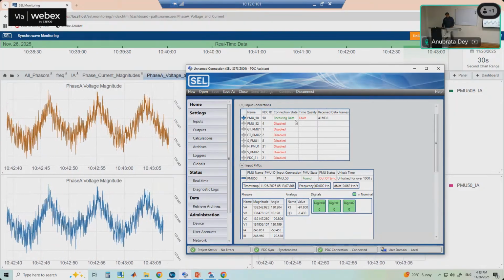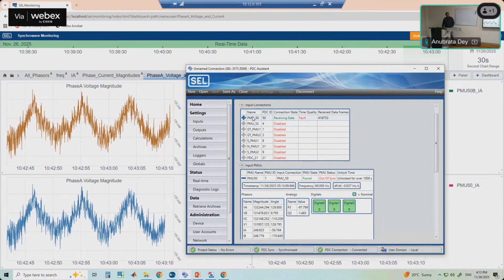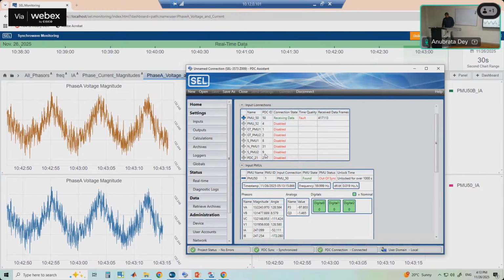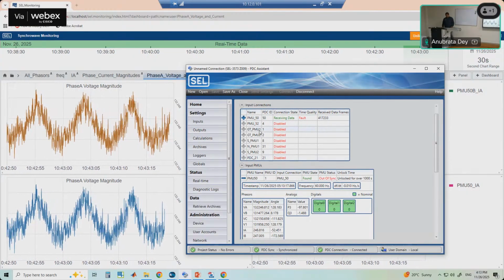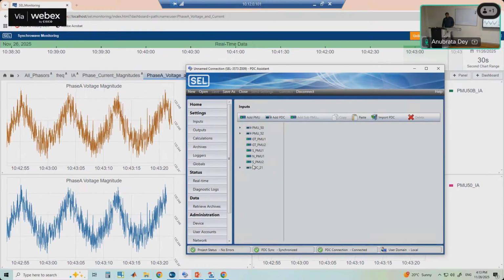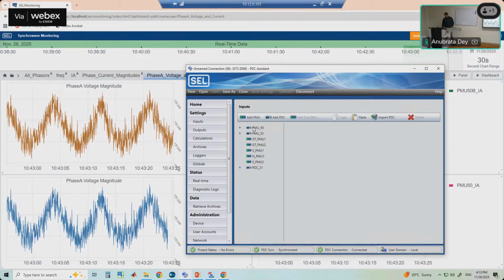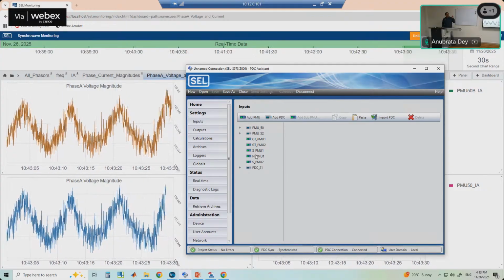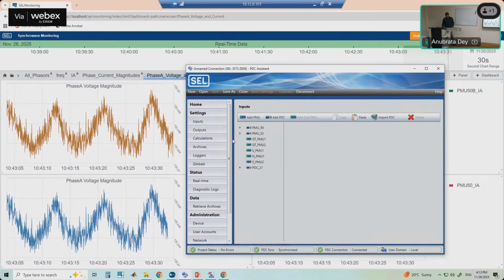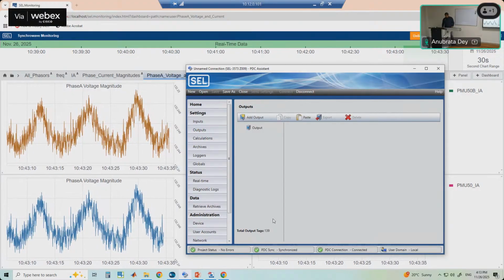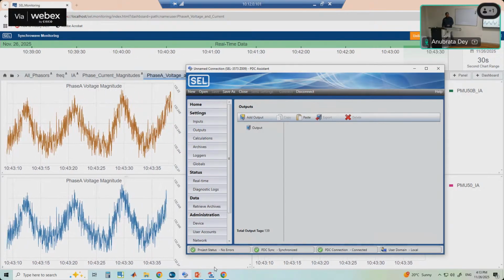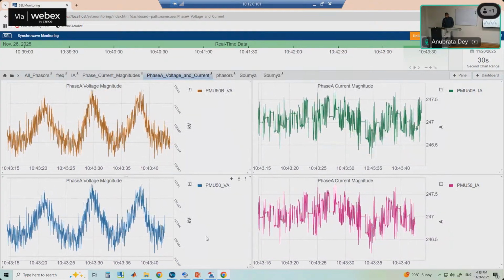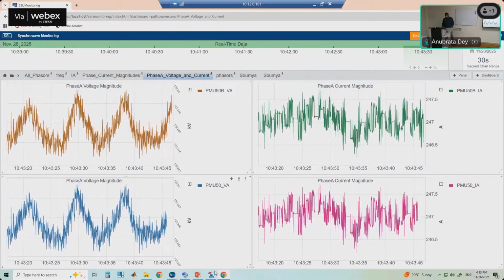The PDC can receive multiple PMUs. So we have these 3 PMUs, 50, 52 and 121. These are hardware PMUs, and all these things we have to configure here. Besides the hardware PMUs, we have some software PMUs, which we can send using the GTNet X2 card. Then this output is what this PDC is sending to this PC. Whatever this software is showing, it is showing on this PC, so the PDC is sending to this device, and there we have configured this output.